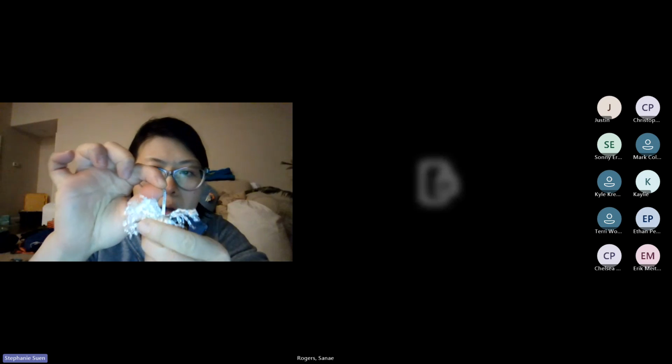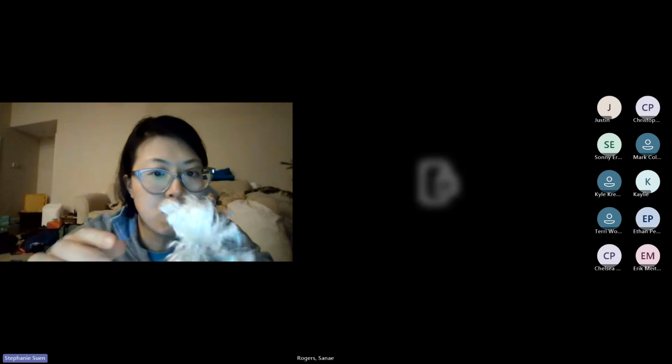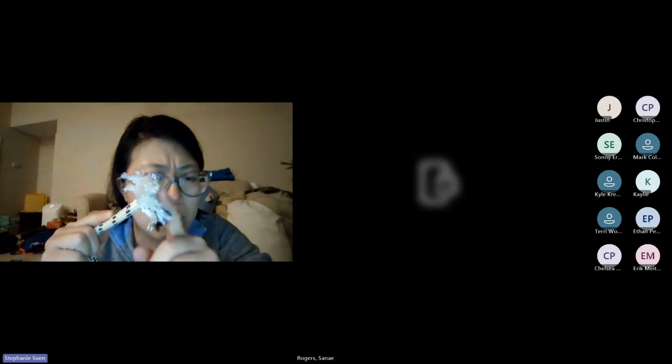This looks like it's PMI rope actually, because I found a tracer tag in it. Some of the manufacturers will put a tracer tag, and you can see there's this little thing that looks like dental floss in there, but it's got some printing on it. Right now, what it says is for life safety. If I were to continue to pull this tracer tag, it probably has the date of manufacture and a little bit more information like that. It's sort of like they're tracking if something were to fail, you could send a piece of rope back and they could figure out what was wrong with it.